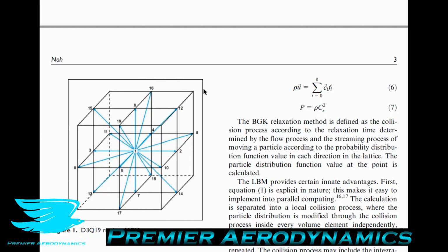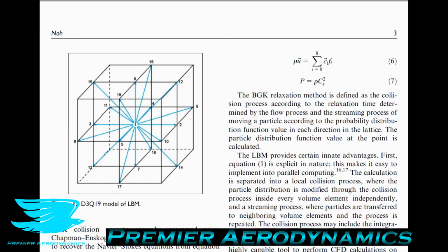So in other words, I covered this in the other podcast that we looked at Lattice Boltzmann method, but I'll just briefly talk about it here. With the Navier-Stokes equations, what they were saying here is you look at a macroscopic point of view, the fluid, what it's doing at each point in the space. But for the Lattice Boltzmann method, you look at individual points in space and you say, okay, this point is representative of these particles in this area. And we assume a certain density, like a distribution of particles in this area as well. And then we calculate the properties from this angle. And we use the Boltzmann equations.